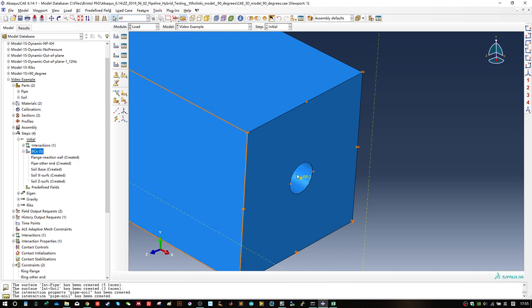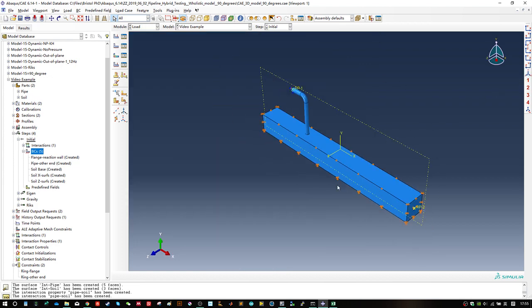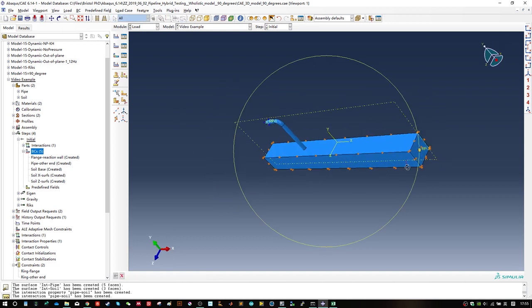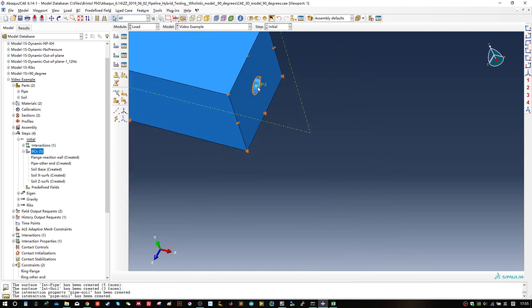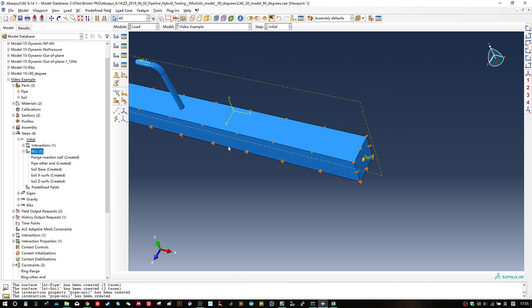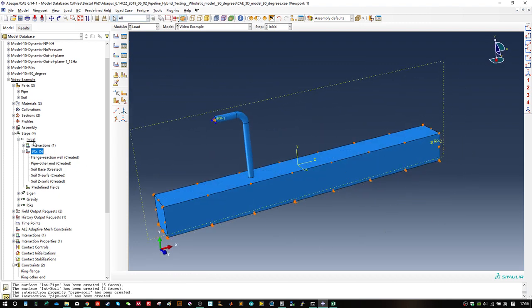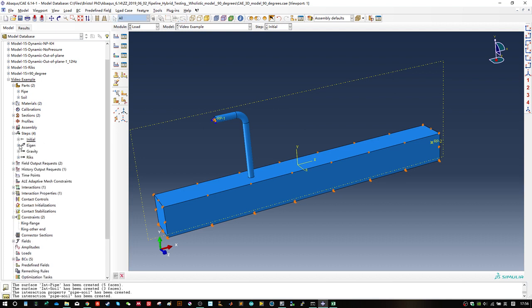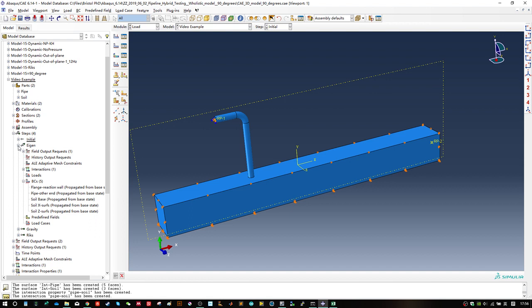Right. You can also consider having a sort of spring here to simulate the infinitely long straight pipe. Or maybe have some beam elements and some springs on the beam element to simulate soil pipe interaction on the less important areas of the pipe. Okay. Then obviously it's just the initial boundary condition. At the eigenanalysis, it's not relevant. It's just keeping the initial boundary conditions, so it's okay.